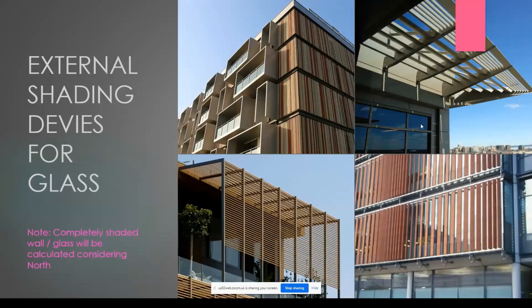And sir, how do we calculate the U value for a wall with external shading elements? As I said, with external shading you do not have direct sunlight on your external wall, so you consider it as a north wall. The U value calculation is the same whether it is a north, east or south wall. Only your ETD, equivalent temperature difference, will vary based on the orientation of the wall. So your equation is area times U times delta T. The U is common for all walls, there is no separate method for north or south. You only need to see what type of material is being used. If they have separate materials, then you need a separate U value calculation. But if they have the same construction, the U value will be the same.